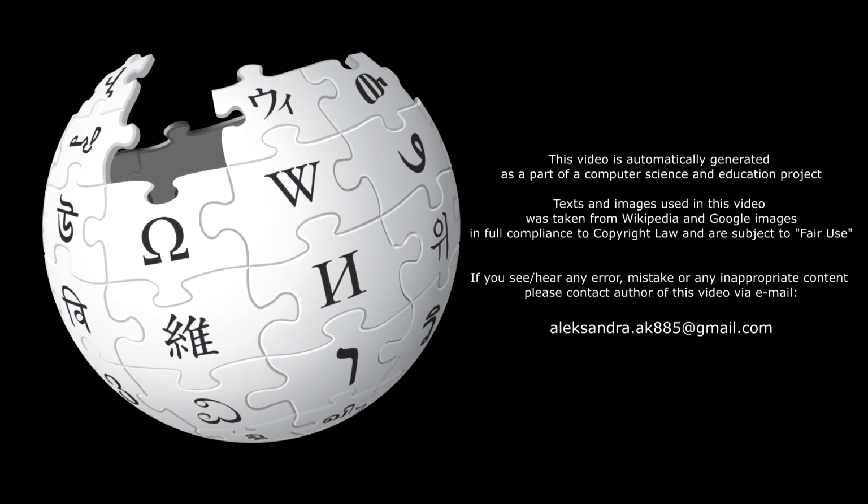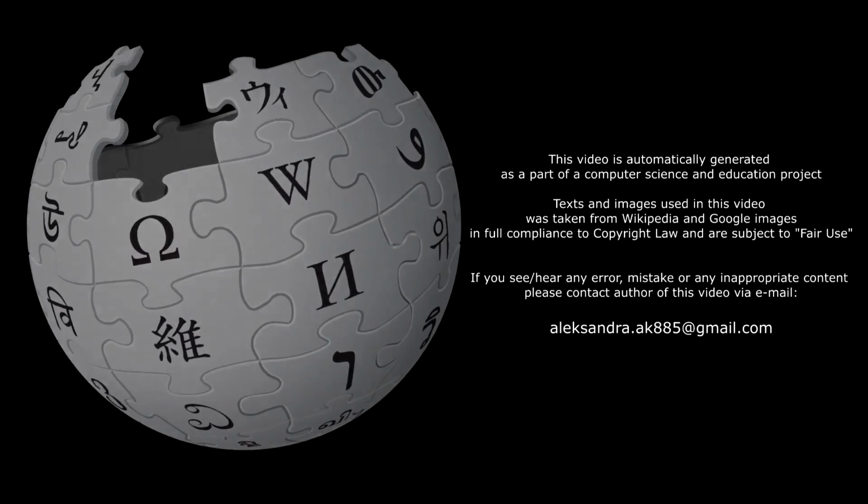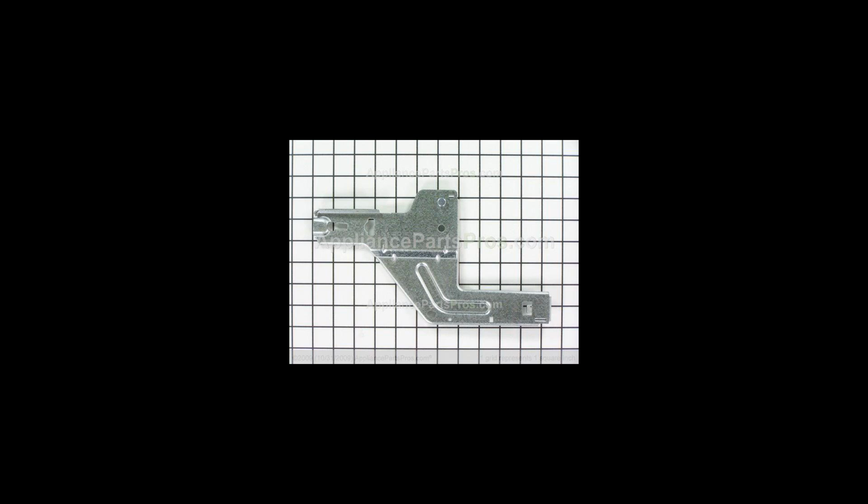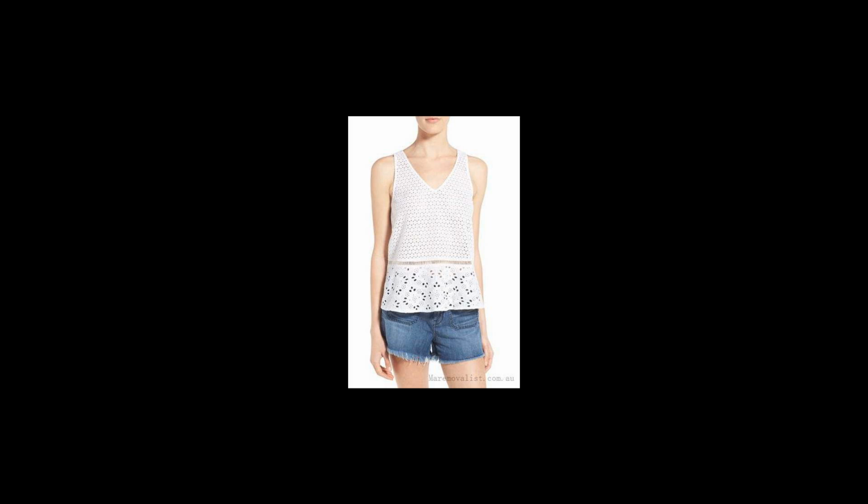A hinge is a mechanical bearing that connects two solid objects, typically allowing only a limited angle of rotation between them. Two objects connected by an ideal hinge rotate relative to each other about a fixed axis of rotation. All other translations or rotations are prevented, and thus a hinge has one degree of freedom. Hinges may be made of flexible material or of moving components.